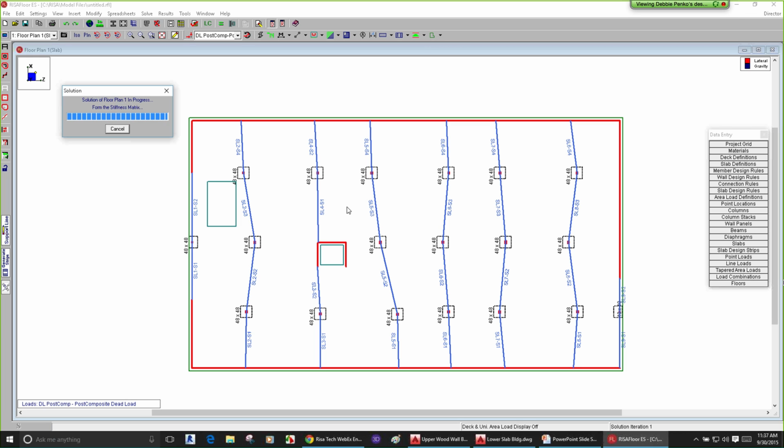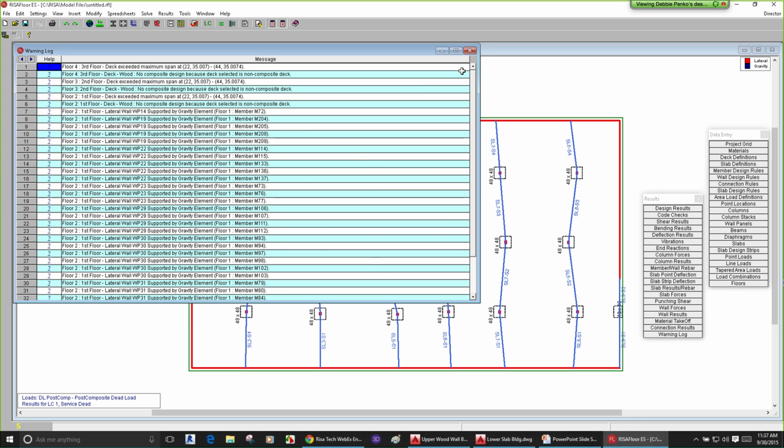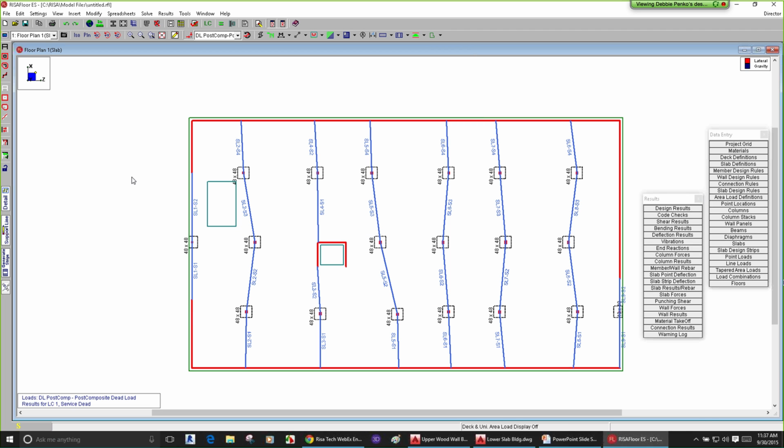A lot of times in design practices, we tend to do just the same so that we won't worry about design issues where one column was thickened and one wasn't, having a shear cap. So capital, shear cap, all those things are terms for what we just added there, which is just a thickening of the slab. And internally, the program is actually thickening the slab in the FEA. So it really is going to distribute the forces differently.